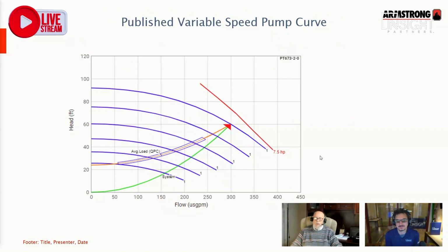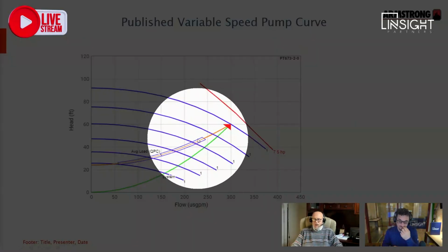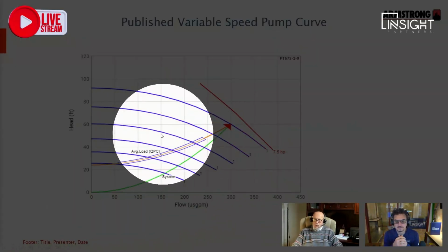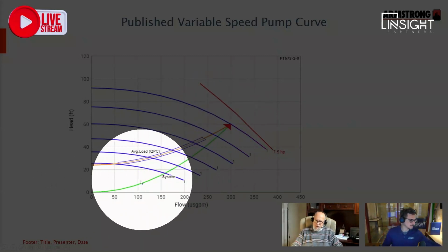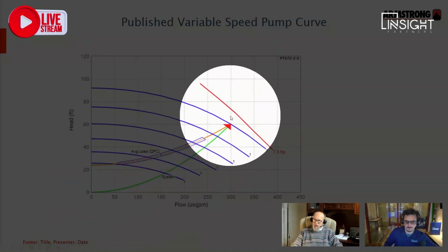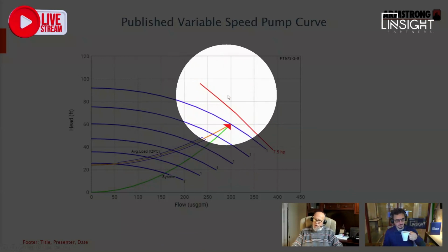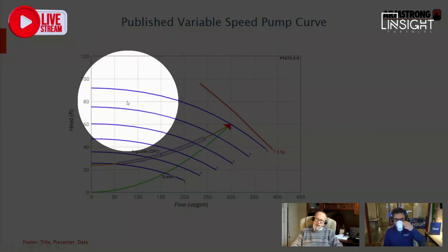If you look at a typical pump curve, one of the things we see today is variable speed pump curves. It looks like a regular pump curve. We've got flow, we've got head, and a system curve, the one I was telling you about that we plot for you. That's your design point, and there's your motor horsepower line. I've stripped a whole bunch of stuff out of this.